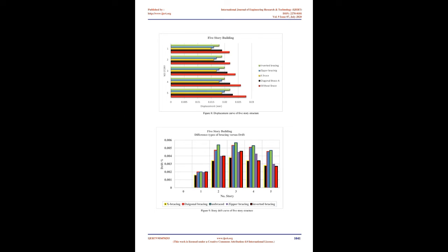Then, they found that the steel bracing system has more strength than the masonry filled wall during the seismic activity. 8. Concentrically and eccentrically braced frames. Steel bracing system is designed primarily to resist the earthquake and wind loads. The members of the steel bracing are intended to work in compression and tension like the truss.